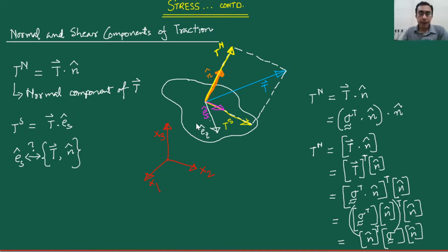That much is okay. However, we are concerned about a single point here. Okay, and we have drawn this plane like this. Okay, and we are drawing the various vectors and we are writing out the various components of the vectors, the t1, the t2, t3, the various things. In fact, the various stress components, the sigma 1 1, sigma 2 2, sigma 3 3, and the rest of them, sigma 1 2, sigma 2 3, sigma 3 1. But whenever we are writing out all those components, please note that they are very specifically referred to this particular choice of the coordinate axis.